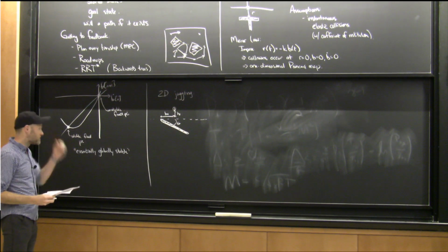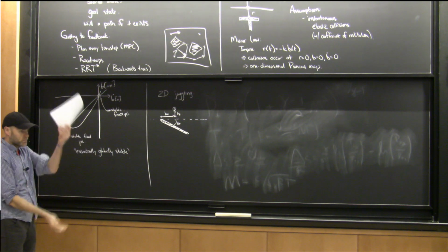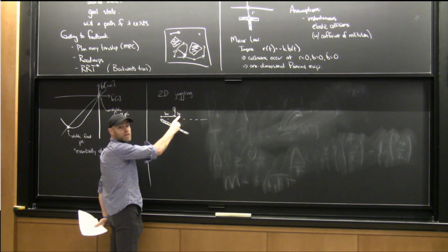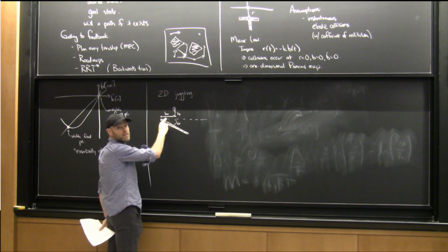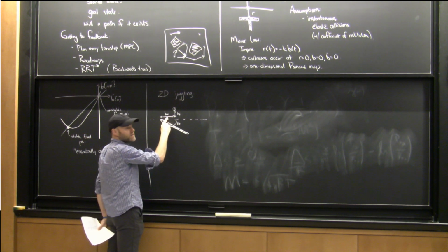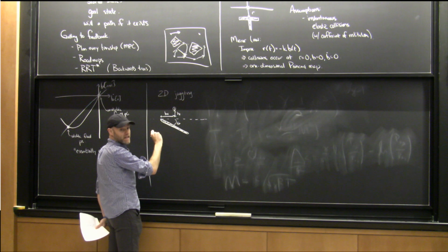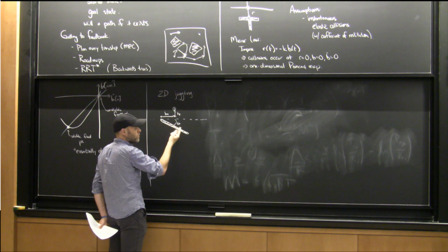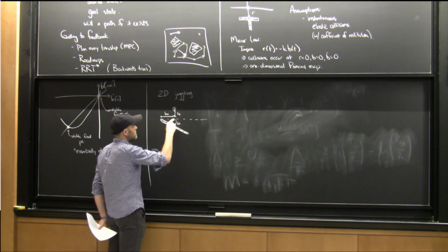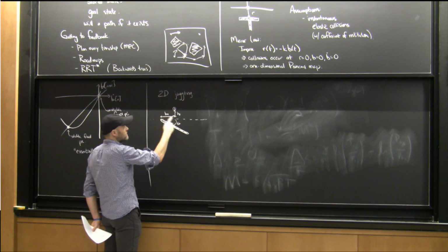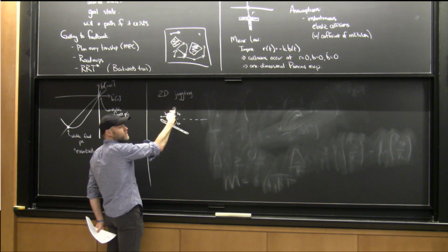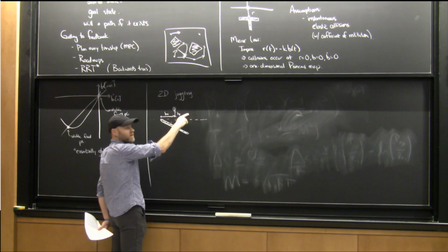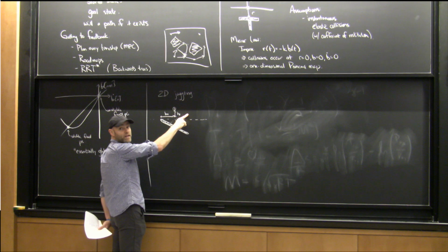You can still do a mirror law type argument, and that will stabilize bz, but it doesn't stabilize bx. The way that you stabilize bx is fairly simple, and again, analogous to what we were talking about in the hopping case. But the rule, which you can bear out with analysis in this simple enough system, is that if bx is too far this way, then you'd like to hit a little bit lower below the line, and it'll add a little bit of velocity in that direction.